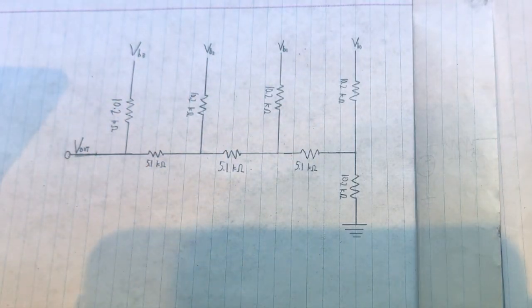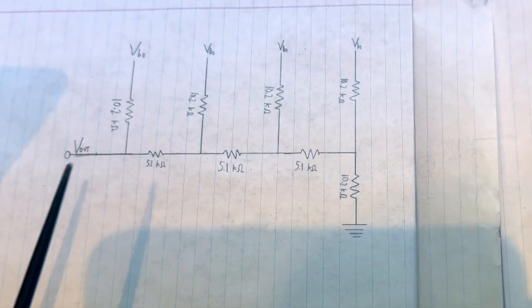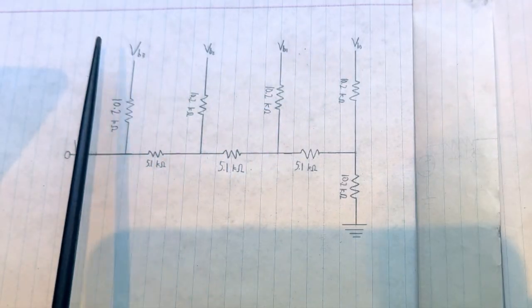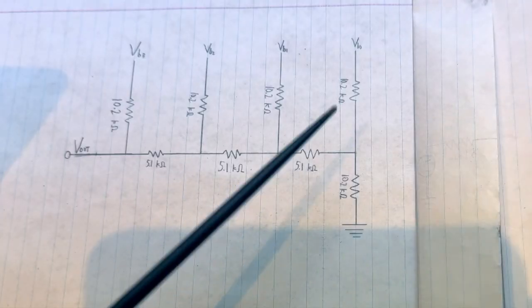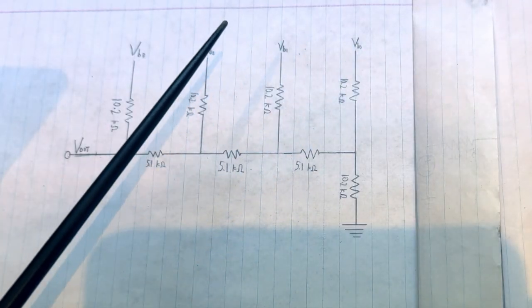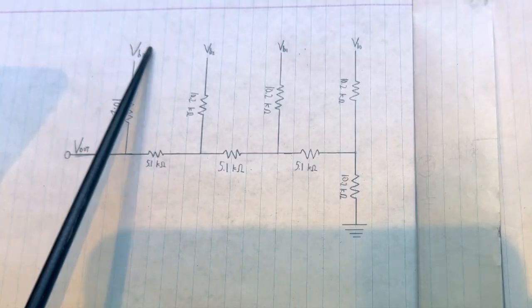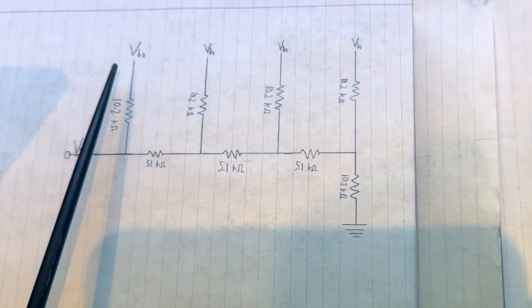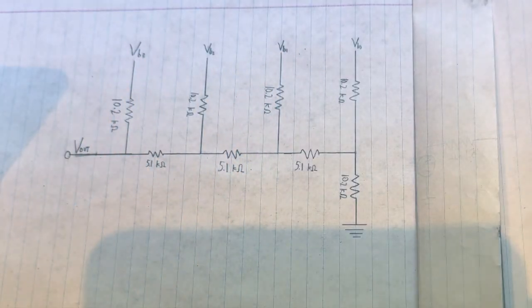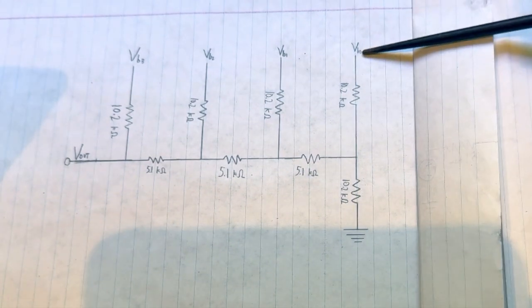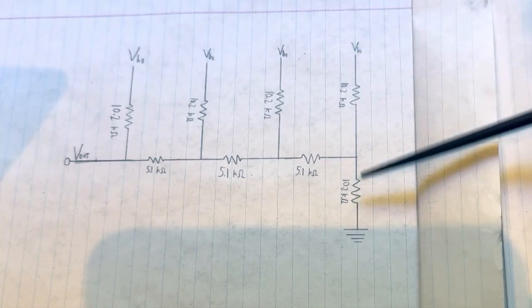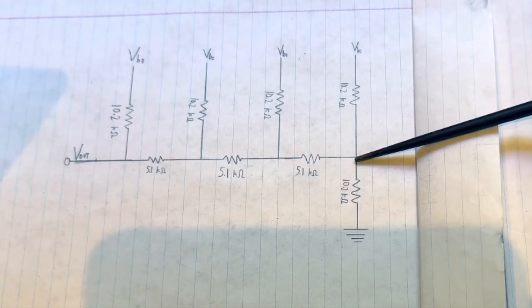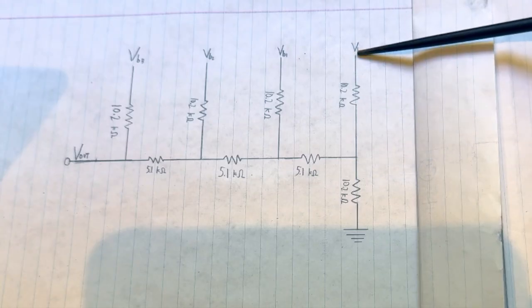Superposition basically states that we short out all the voltage sources except for the one being calculated for. So in this example, we'll do bit 0. You do this for each of the sources that are on, and then you add them up. For bit 0, we have a voltage here, 9 volts in this circuit, across two equal resistors going to ground. So we know here will be half of bit 0.